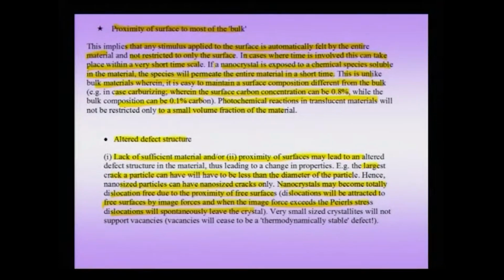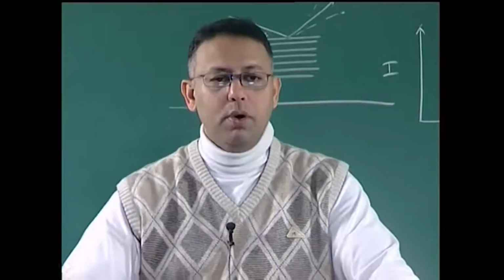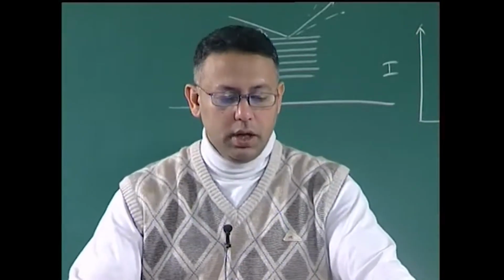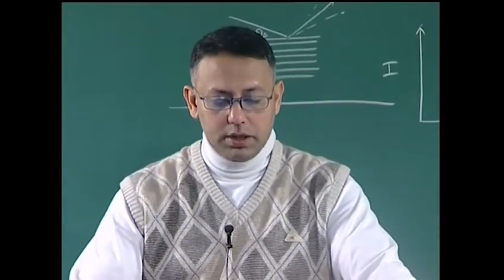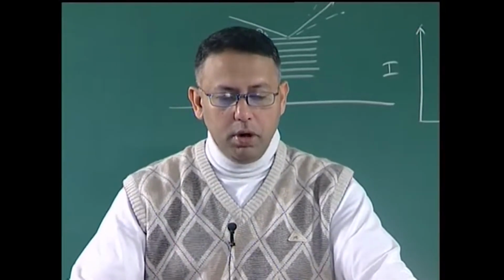Very small size crystals may even not support vacancies. That means vacancies will cease to be a thermodynamically stable defect in nanocrystals. So, this may also happen, and we will have a little more to say about this topic of altered defect structure in one of the coming lectures. But the important point is that